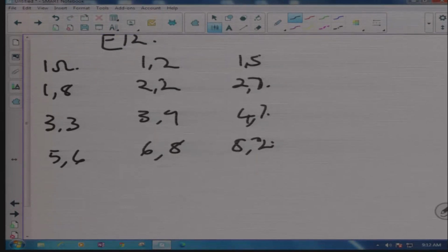Sometimes when you do your calculation, you find your answer being somewhere between 1.2 and 1.5. It is advisable that for better calculation, you redo your problem. Instead of using 1.2, you'll use 1.5. And that is the way we do it. Now look at this 8.2. Assuming that you do your calculation, you find your answer is 9.2. You use the next one in line. After 8.2, the next one is 1 there, but it would be like 10 ohms.